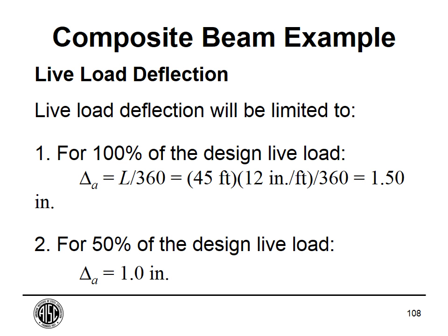The reason it's preliminary is that it's good for strength, we know that, but as you'll see, I had to change it once we got to the deflection calculations. And I'm not sure if the owner wants to hold these same deflection limits as he had in the example problem. For all I know, this went from a dance floor to a warehouse. But we'll say he wants to go ahead and hold these limits.